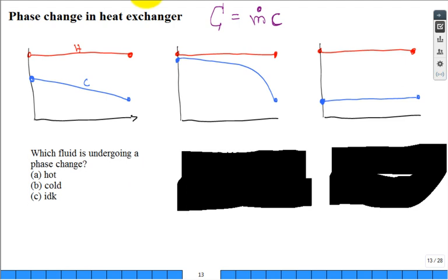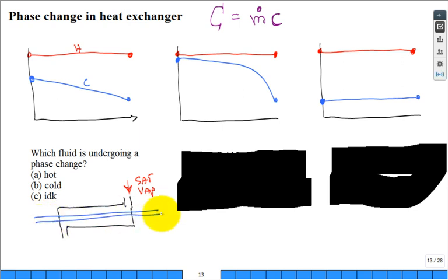So this type of heat exchanger is fairly common. What you have is a little inlet, and then it comes out, and then you have a little outlet. And so maybe on the shell side, you bring in some hot fluid that is saturated vapor, and it flows over a tube that runs through the middle that's cold. The saturated vapor is going to see a cold surface. What's it going to do on the outside of that tube? Condense and drip off. And then with a little help from gravity, you could collect it and bring it out as saturated liquid. You'd just have a little puddle down here and drain it, slope it a little bit, and you would bring it out.